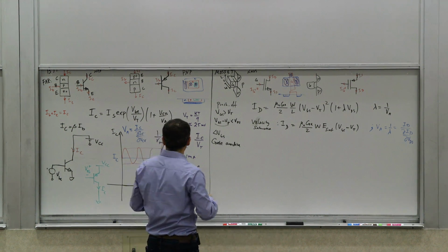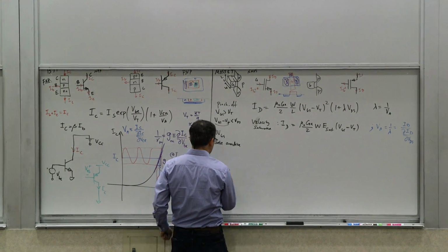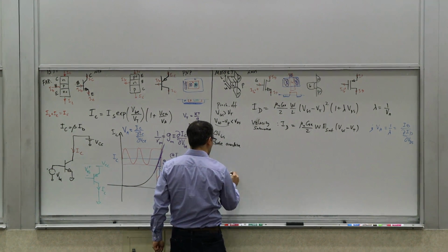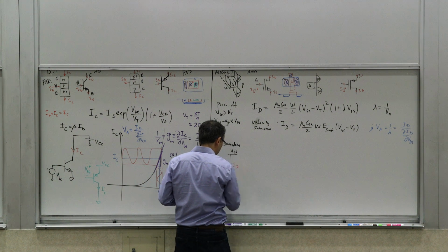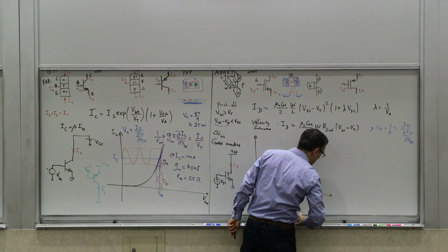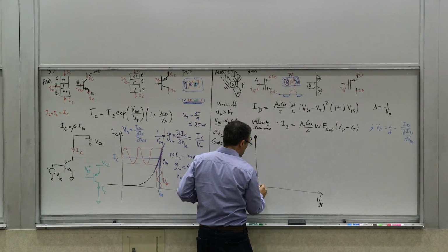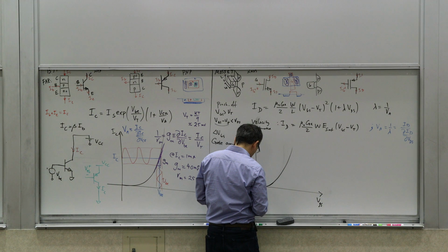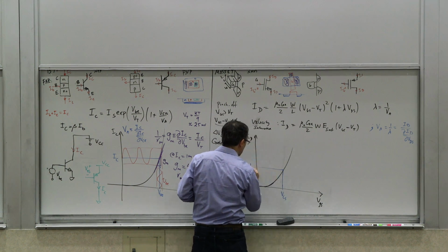If you want to come up with a similar treatment as this one, you have to bias your transistor in a certain way. Say I have an NMOS. I apply some VGS here, I apply a VDD, and I monitor my drain current, ID, versus this VGS. And we plot that. Depending on what kind of behavior you have, it's either quadratic, or linear, or something in between. It doesn't really matter which kind it is. Again, you have an operation point: some VGS that corresponds to some ID.